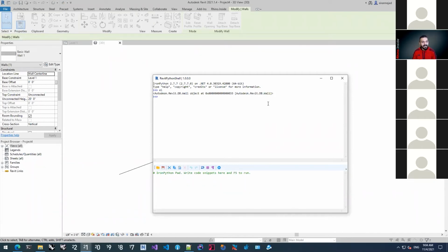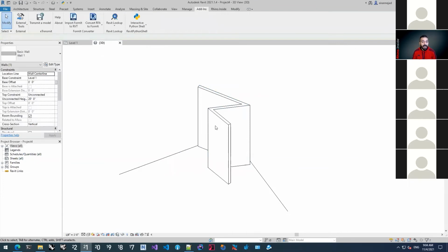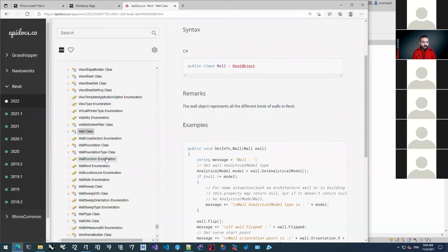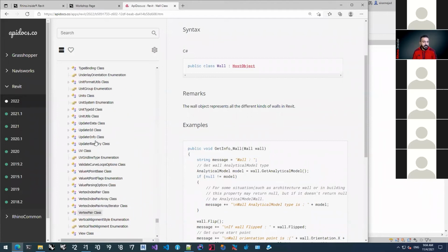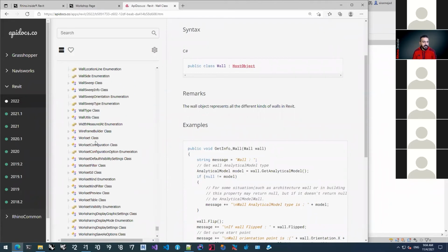That means that they haven't really created anything specific for that geometry or whatever that you're seeing in a Revit model, right? So just know that this is one of the inconsistencies in the Revit API. Not everything that you see here has a specific type. Basically, I guess that's the most important thing that you want to know at this point, that everything gets derived from DB Element, and there are specific types for some things. Not everything's available through that.